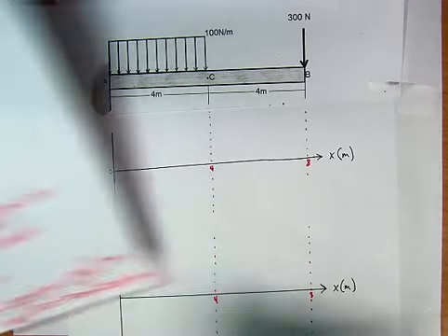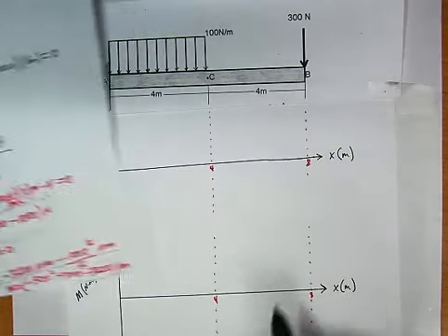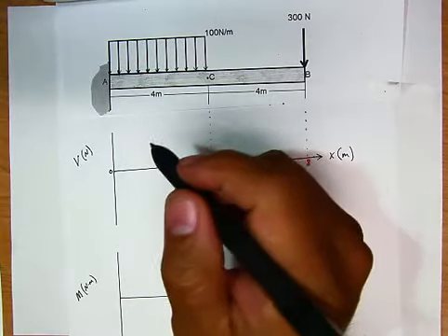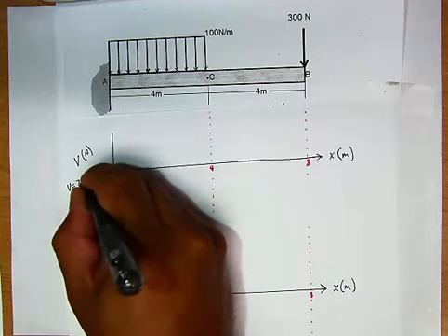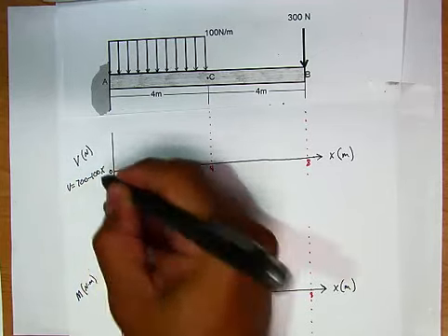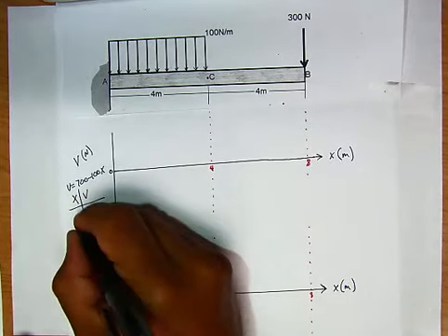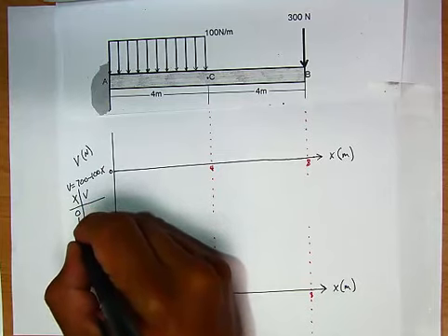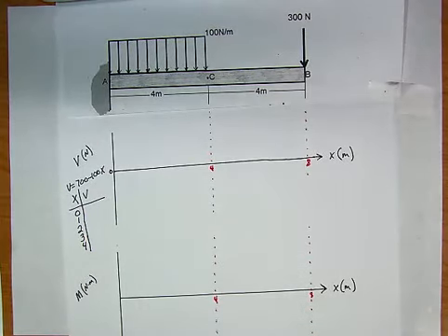Alright. Now, let us take a look at what's happening here and here. And by that, we go back to our first equations. In our shear equation, we're going to get V equals 700 minus 100x. And we're going to create a table. Very nice table. Remember that our range, I call it range, in reality our domain, is 0, 1, 2, 3, and 4. So we get our calculators and find out those values right there.